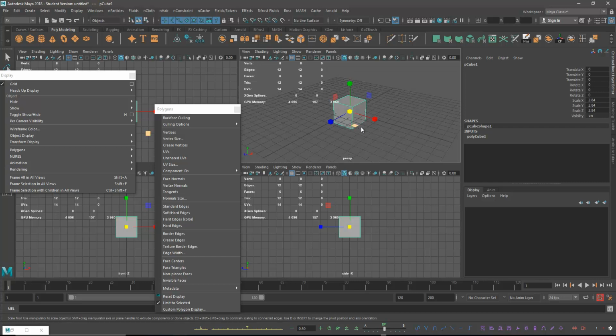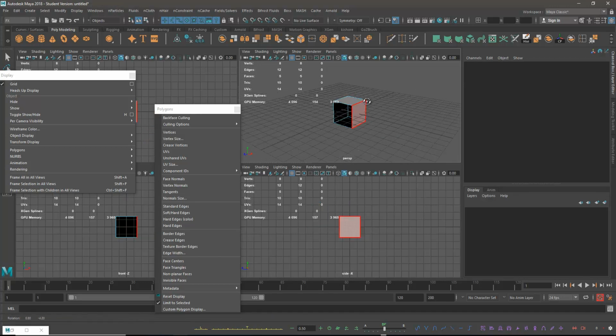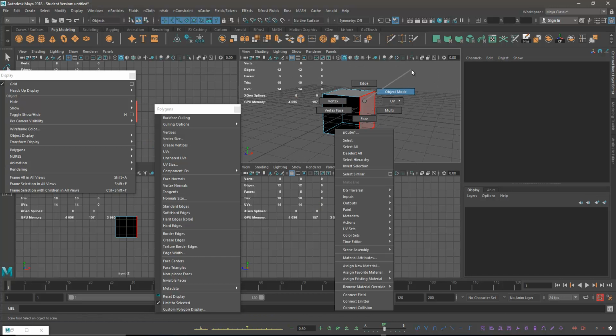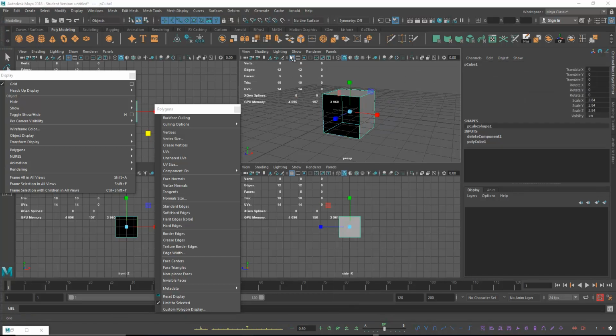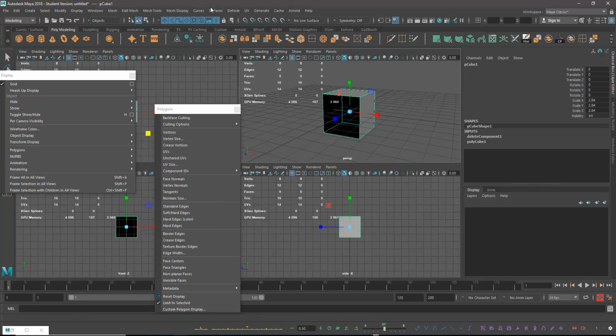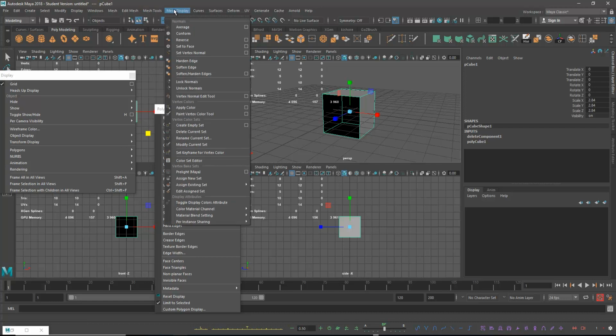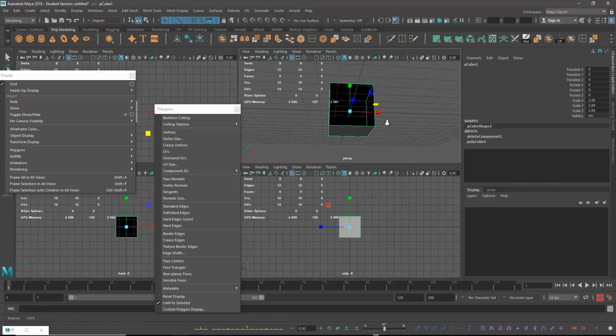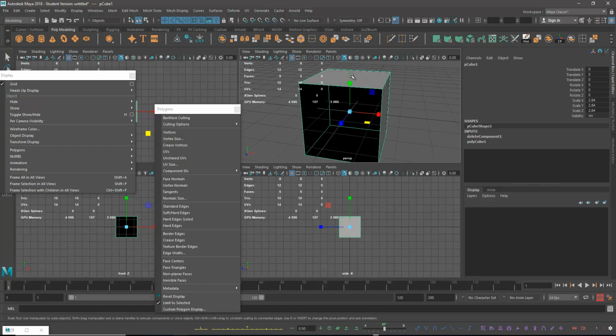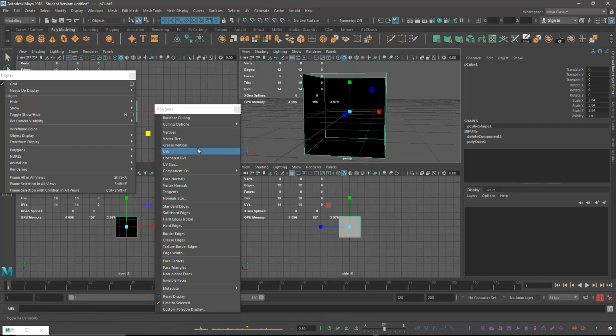See, if I remove one face, select the face and delete. Inside it is very dark, but outside it's shaded with the gray color. So I'm just selecting the box. Here you can see, go to the polygons, so modeling here. Here we are at the modeling polygons. You can see reverse. First of all, let's enable face normals. So with face normals, you can see they are very small, right? There are green color lines, right? So you can increase the face normal size.